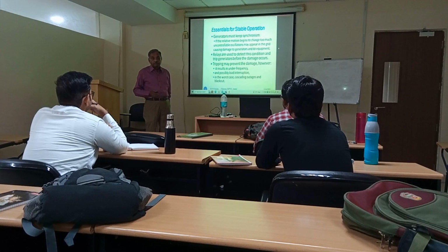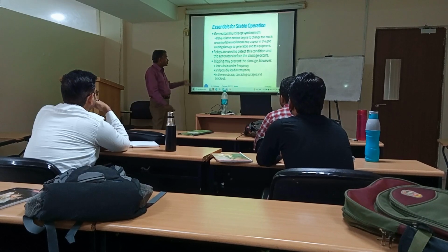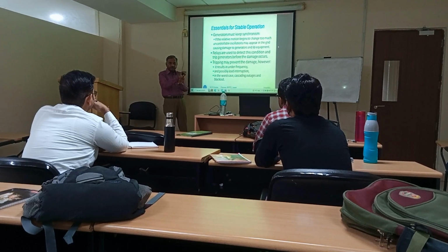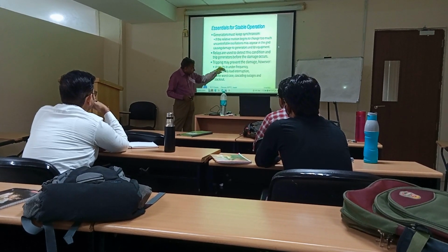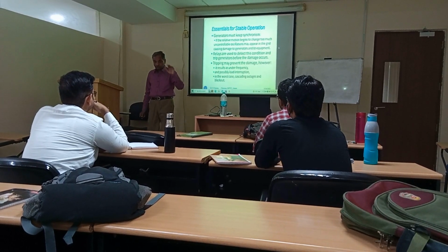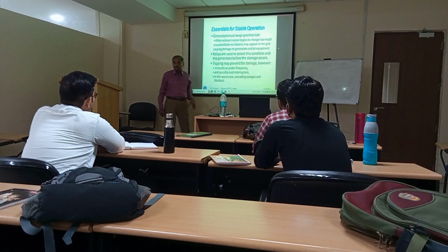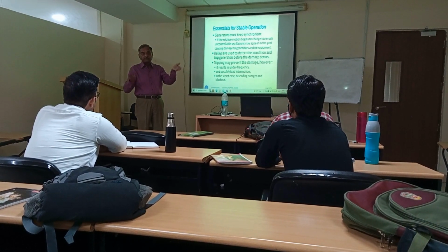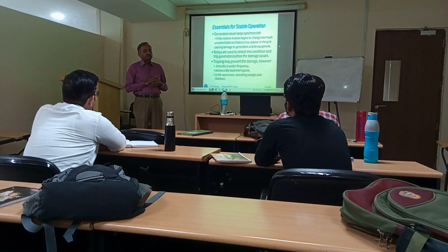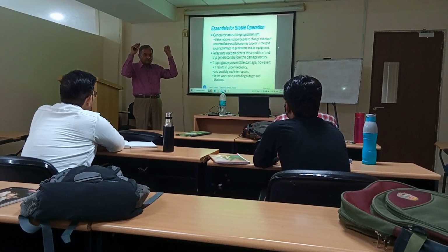If the generator trips, then whatever output it was giving is lost. Tripping may prevent damage to the generator, but as a result there is an under frequency. There is a possibility of a load interruption, or in the worst case, cascading. Other machines get overloaded. They also trip, and this phenomenon goes like a virus, and the whole system collapses.